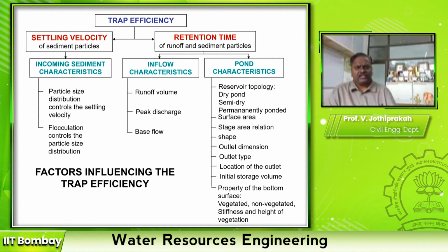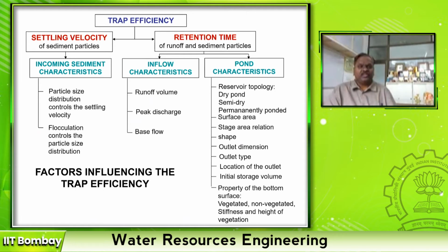In that, we are looking at how to estimate the sediment dead storage level, which is based on the trap efficiency. This trap efficiency is also estimated every year for large dams, so as to estimate how much the volume of water is reduced due to sedimentation. That is why these trap efficiency studies are very important nowadays in water resource management.